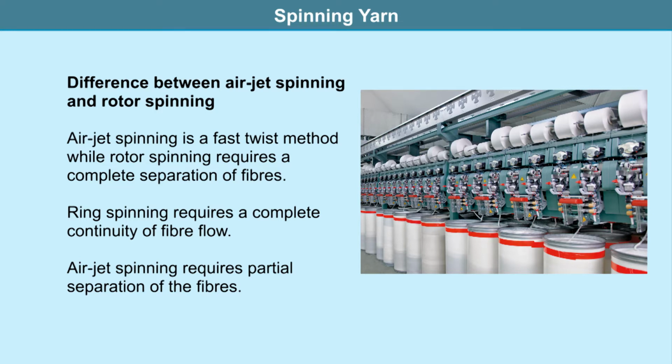Another point is that air jet spinning requires a very clean cotton with a long staple length. Usually the cotton sliver goes through a 3-step drawing operation. Air jet spinning frames use a rotating disc to convert cotton sliver to yarn. The tubs of sliver are loaded down each side of the frame. As the sliver feeds through faster and faster sets of rollers, the sliver reduces in bulk. The spinning action occurs between the last roller grip and the spinning disc.